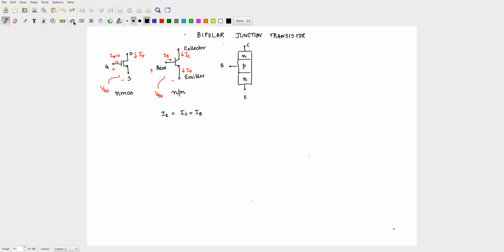So, we should draw the characteristics, but before that you possibly have already seen this somewhere, that the base current IB, right, base current IB is what? Yeah. So, it is IC divided by beta, and beta for a typical transistor is about 100. Okay. It will vary, maybe 50, maybe 100, maybe today 50, tomorrow 100. If you take it near the generator where it is very hot, it may become something else. Okay. It varies, but it is of this order.